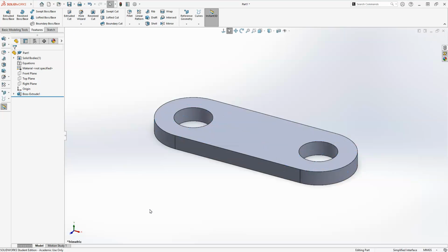Okay, all right. Now I want to kind of revolve this. And this is where I would like to see Solidworks improve on one thing. The thing that I would love for it to do is allow me to select that axis that's running through here. So you're going to see that I want to revolve this, or not revolve it, I'm sorry, I want to use a circular pattern.